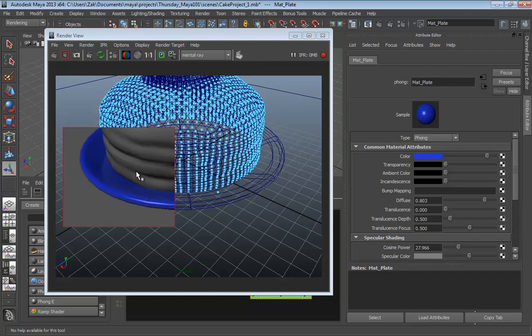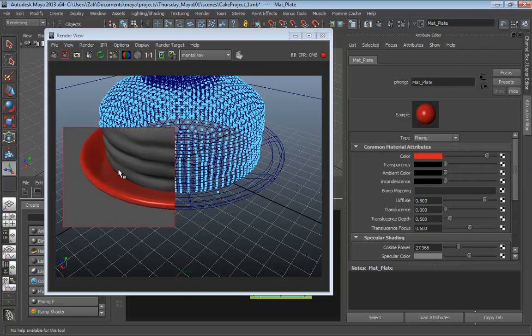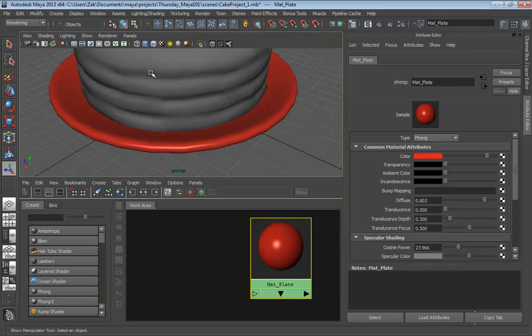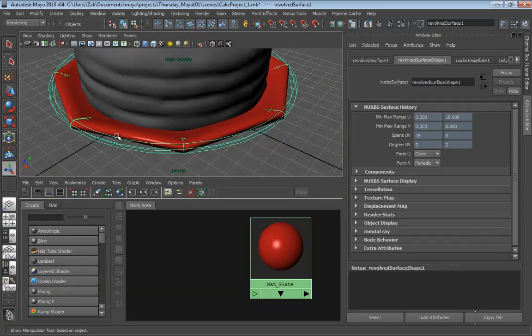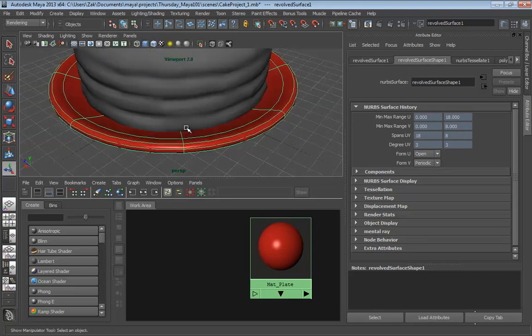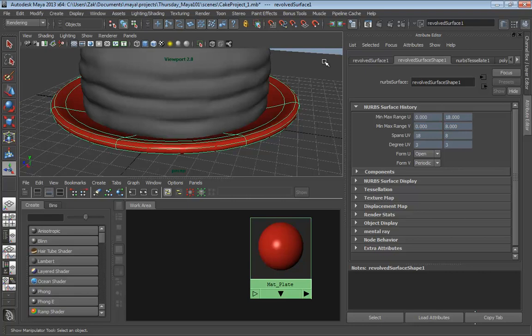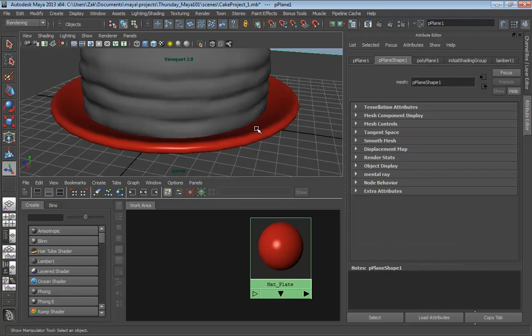Now, I generally don't use this that much anymore. I'm not going to call it obsolete in any way. You can still use it for all kinds of fun stuff. However, with the advent of high-quality rendering, which makes your plate look funny until you hit the 3 key on it, by the way, or Viewport 2.0, which works really well on my computer, I find I really don't need it. I can get just as much of a preview as I need out of that.